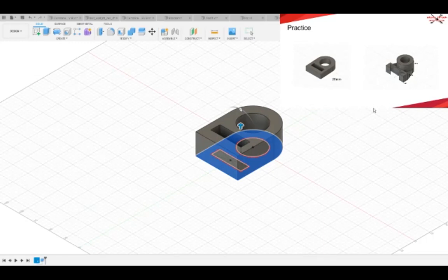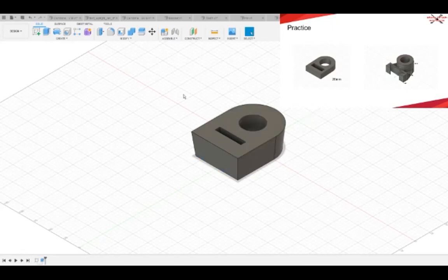So we'll set it to a distance, because that's nice and arbitrary. We have a distance that would be arbitrarily set to 35 millimeters, and you have a taper angle if you want to put a draft on it. So let's say we set this to, I don't know, 6. Now it's a little chunky at the top and a little thin at the bottom, but for the sake of ease of work, we're just going to make this 0, because normally most of the stuff we tend to make doesn't usually have that type of taper, because I don't think there's anything we have in the shop that can make that.